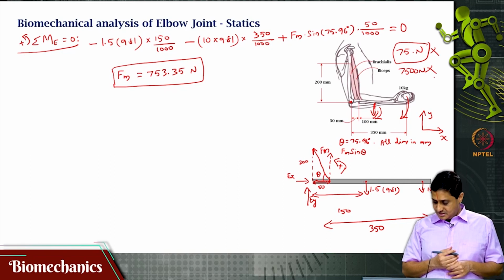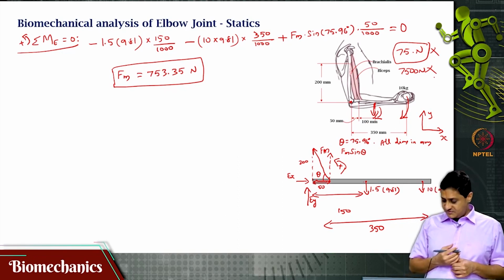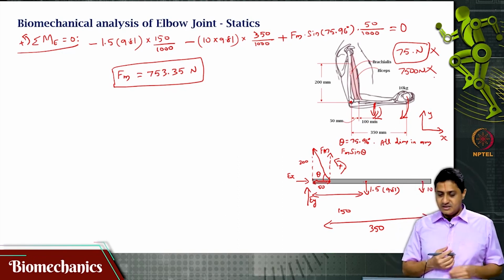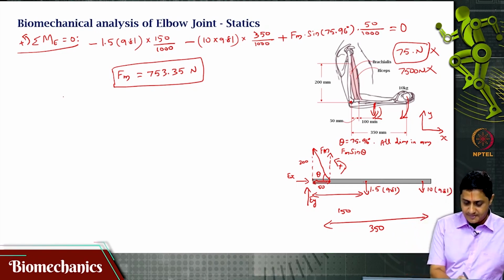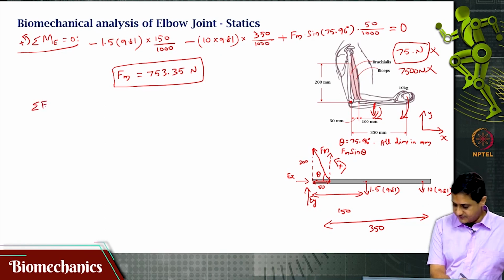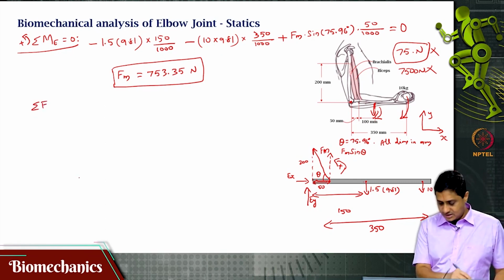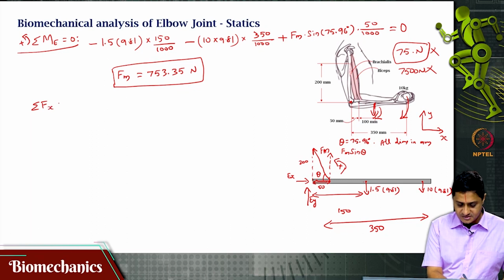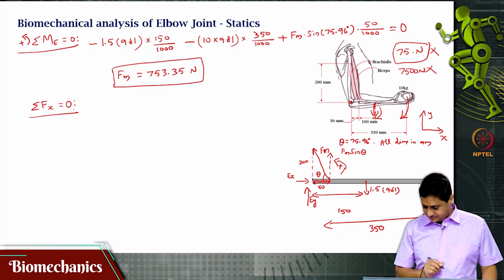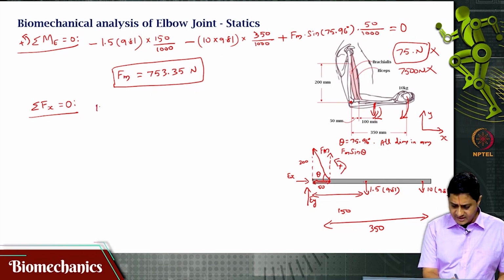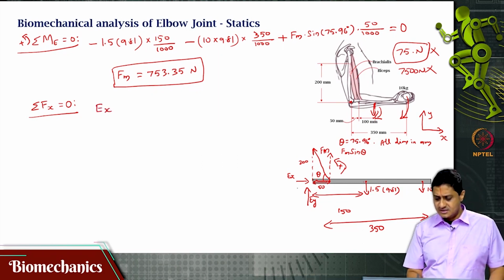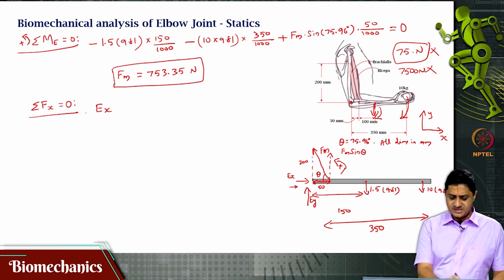Okay. We are not done yet, because we will also have to find the reaction forces, is it not? Let us not assume that we are done, because I am interested in finding the reaction forces. Sigma Fx equal to 0 will give me what are the various forces that are acting along the x direction. Well, Ex is along the positive x direction, so plus Ex.